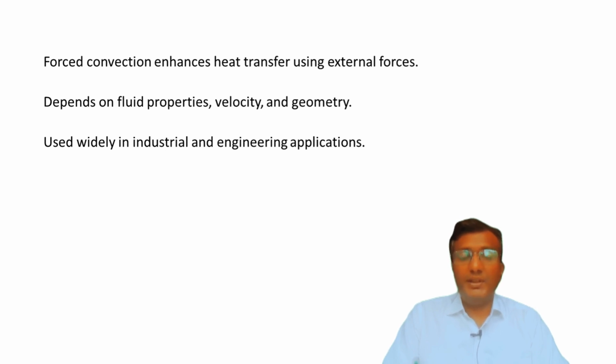Forced convection is integral to many engineering applications. In automotive cooling systems, radiators use forced convection to dissipate engine heat, with the fan driving air over the fins and the coolant flowing through the tubes. Air conditioning and refrigeration systems rely on forced convection to transfer heat via evaporators and condensers, ensuring efficient cooling. Heat exchangers in industries such as power plants or chemical processing use forced convection to transfer heat between fluids, often through tube bundles or plate systems.